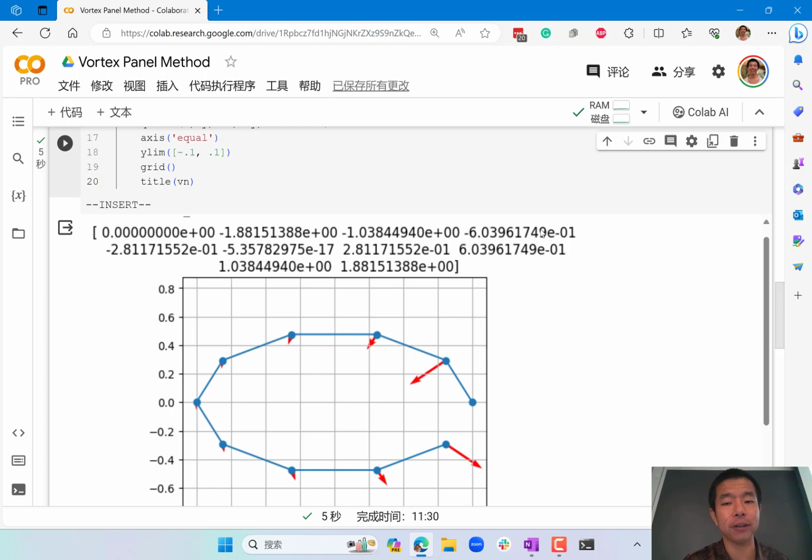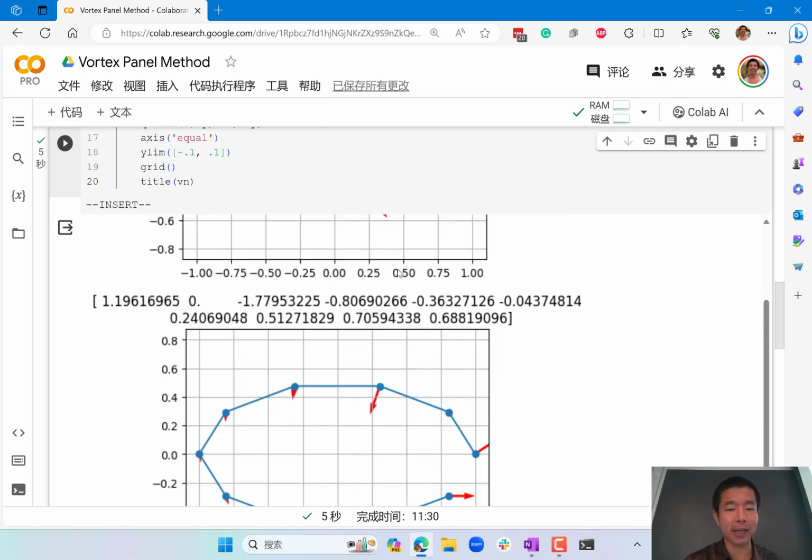And the next one, also negative, the magnitude is even smaller. When you get to the leading edge, it induces a velocity exactly in the vertical direction, so no normal component. Then starting from the lower surface, it induces a velocity in the positive normal direction. Similar things you can say about the later ones.